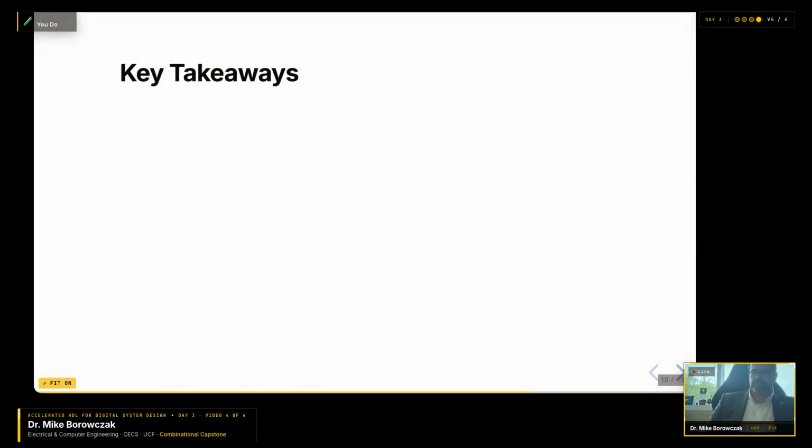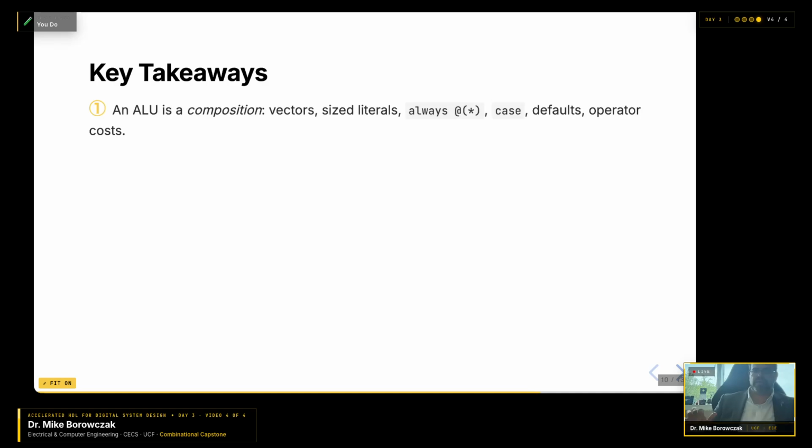So, big takeaways. The ALU is a great composition of everything we've seen so far. Vectors, size literals, using the always with a wildcard sensitivity list, the case statement, defaults, initializations, operator costs, all of it is in the ALU. So take some time, especially with the lab that's associated with this video series. Do the lab. You will learn a lot, and you will learn by doing.